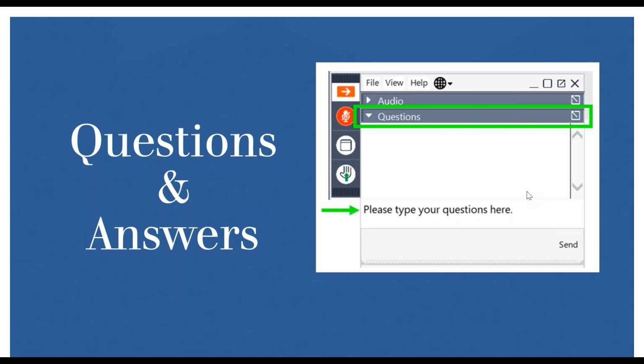Agus? For the PID sensor detectors, it really depends on the intended use. If it's used for personal monitoring, gas detectors with PID sensors should be used instead of tubes. The PID sensors are used to detect volatile organic compounds, and can detect a very low range. Although the sensor will need to be checked and calibrated at intervals, and calibration probably requires some training, you will also require consumables such as the calibration gas in order to maintain the calibration for the PID sensors.